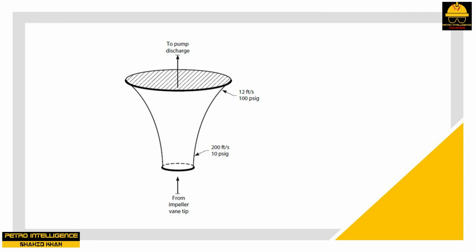The volute, which is also called the diffuser, is shaped like a cone. It widens out in the manner illustrated in the picture. As the liquid flows into the wider section of the volute, its velocity is reduced, and the lost velocity is converted, well, not into pressure, but into feet of head.